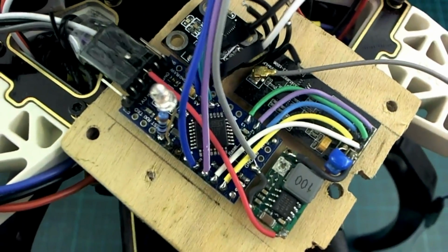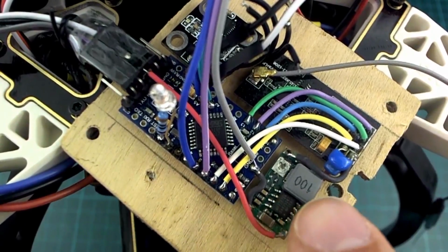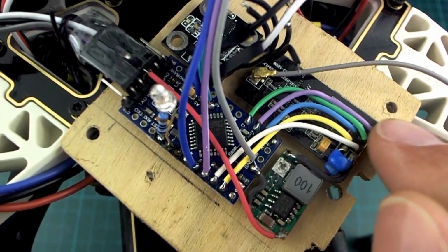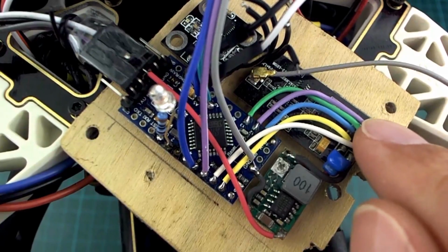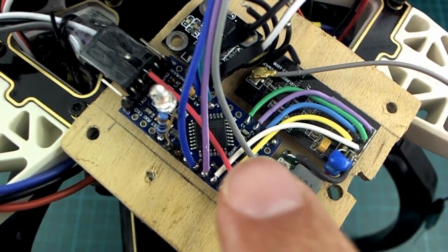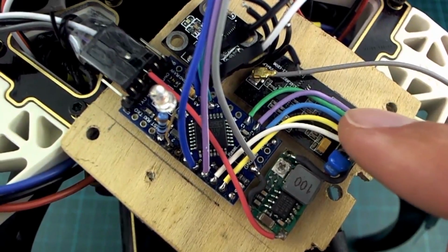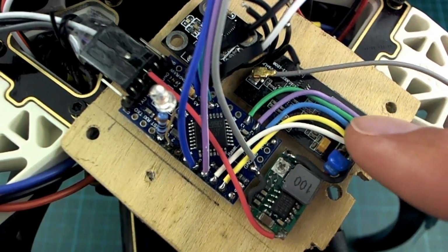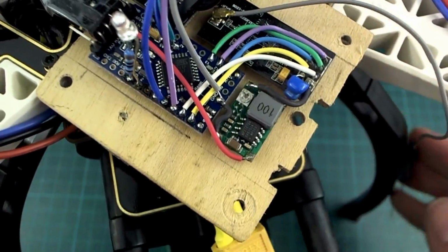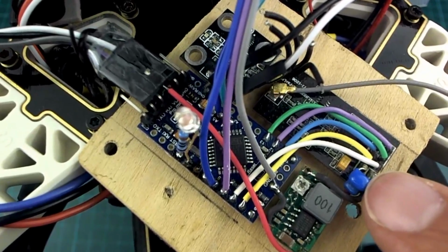Anyway, back to the controller. Being a 5 volt one here, I have had to use a little voltage step down regulator to power the radio module. So this is again at 3 volts. And I think I did set this one to 3 volts, not 3.3, because if you're using 5 volt signals, according to the datasheet again, you should be powering it with 3 volts instead of 3.3. So that's the antenna there, it just goes down there. Again, a couple of little capacitors on there seem to work quite well.